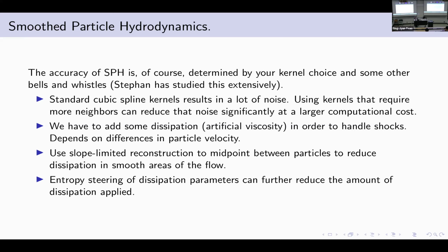The particles get closer to each other, so you have higher resolution automatically. No, we don't add more, but as the particles get closer together, you automatically have a smaller smoothing length. I should probably say that in our simulations, we adjust the smoothing kernel dynamically through the simulation so that we always have the same number of neighbors within our kernel.